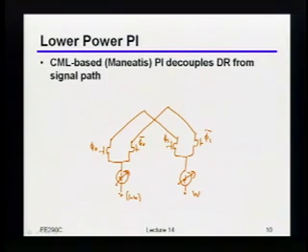So it turns out that what you're typically going to have to do is dump it into a programmable resistor. There's lots of different ways to build a programmable resistor, but one that turns out to be pretty nice because it's fairly linear from the standpoint of the control voltage is the so-called Maniatis load. I'll draw it in 1 second. Maniatis is the last name of the guy who invented this. I mentioned him previously because he was also the guy that did a lot of the preliminary self-biased PLL work. So I'll just draw what this looks like, and then we'll see how it goes.